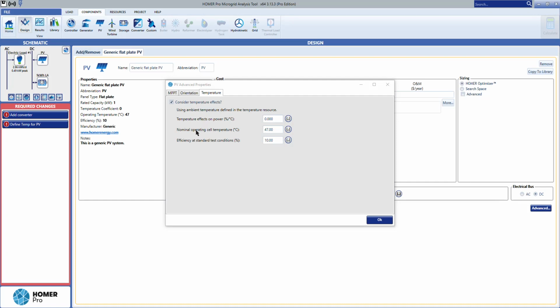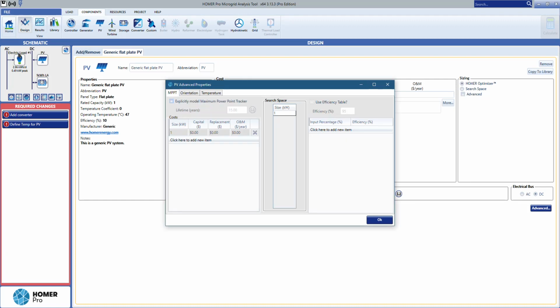there is this efficiency of 95%, but we don't have charge controller in the components of the HOMER Pro. We have a controller which is something else, and we have a converter. Usually the charge controllers can be considered with the battery systems, but also in HOMER there is not this possibility to add this charge controller inside the storage system. But there are many devices.